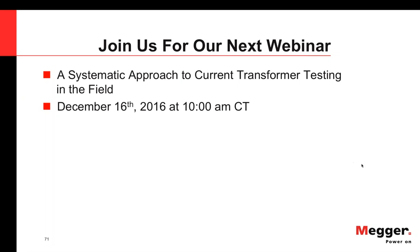Okay, let's see. Next question is, harmonic analysis. If there is a high harmonic in a specific current phase for a wind farm, what could be the cause? Should I be checking at the power electronic devices of the turbine or the PCC? Both. Check at both, but the actual inverters will generate high harmonic content, and typically, like I said, those will be seen around the 35th to the 45th. And it is those switching inverters that are creating those high harmonics.